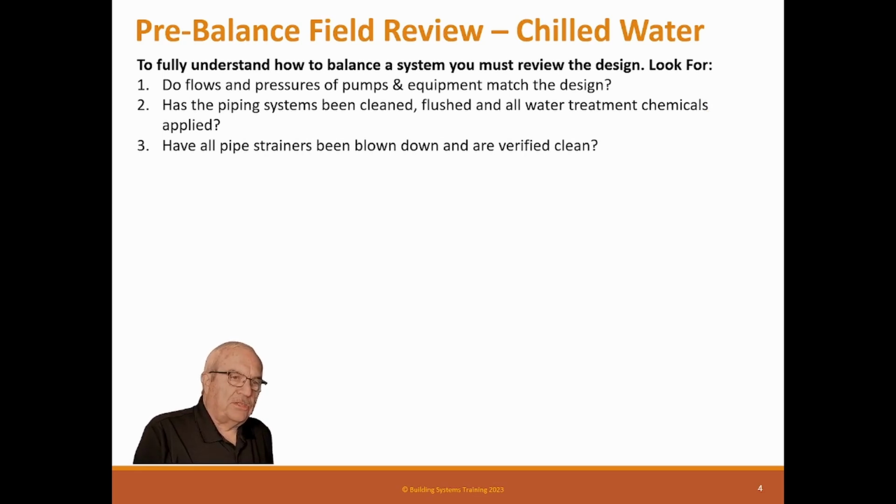So the large system pipe strainers normally have a sieve with large holes in it that are slightly smaller than the holes in the volute of the pump to keep anything from clogging the pump. Inside of that is a fine screen sieve. That's called a startup strainer. What that's designed to do is to catch all the weld slag or anything that's in the pipe that shouldn't be there. And that's intended to be taken out and removed after they clean the system and started it up, and it's to be taken out before you test and balance.